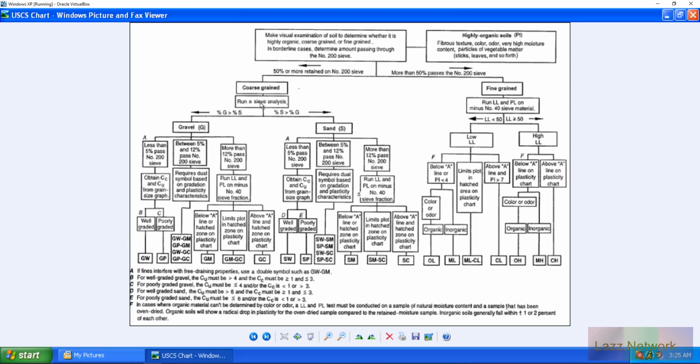So even though I'm saying that in general, in all honesty, you would be able to tell which one is which. But if you only did just, hey, we have this gravel sand mix, and we just want to know generally how much gravel is in here, then really you only have to sieve it over a number 4 and see however much is retained on it.